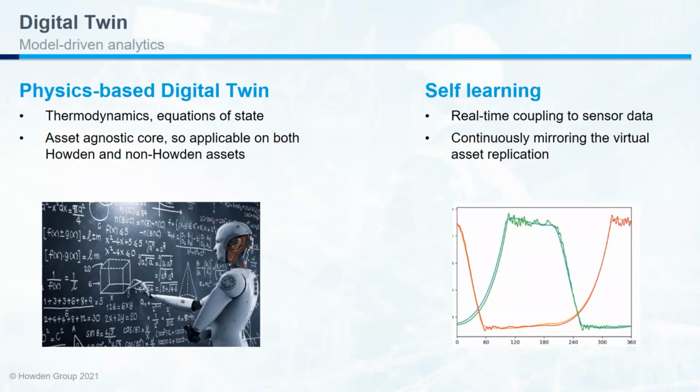It's self-learning. On the right, you can see an example of a PV chart for a reciprocating compressor. I use this example as this is something we currently have in place. You can see an overlay of measured values and calculated values. If we see any deviations in the PV chart between these data sets, this gives an indication of failures, in this case with a compressor.